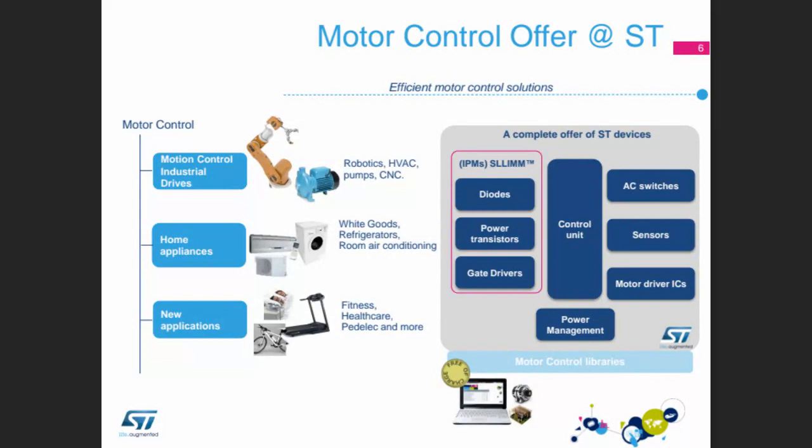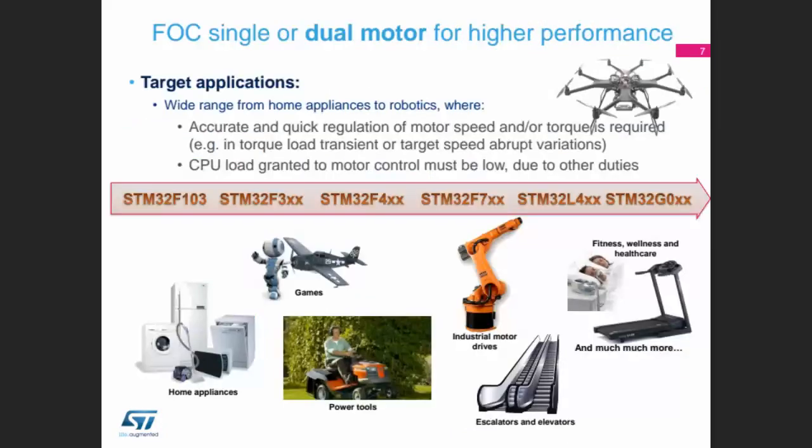For example, you need to use a sensor for position feedback reading. In your microcontroller, you have an ADC. You can adjust your ADC features, and then you can read the sensors, Hall sensors, etc., voltage sensor, current sensor, and then maybe you can control your motor easily.